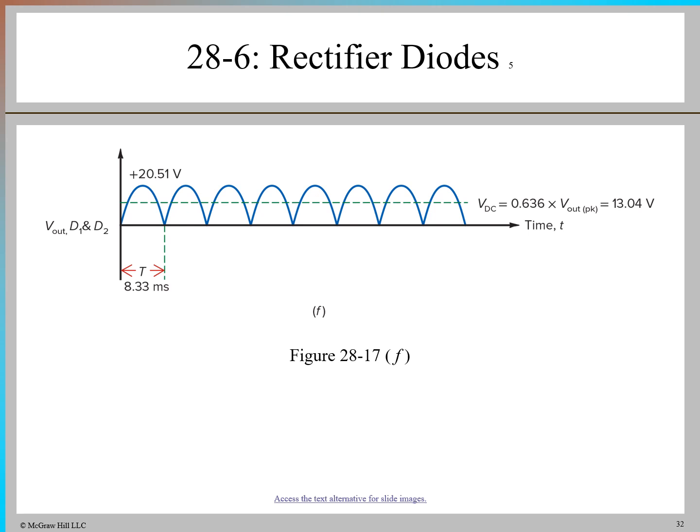The graph of a full-wave rectifier shows the transformation of an input AC sine wave into a pulsating DC output. Notice how both the positive and negative half cycles of the AC input are rectified, producing a continuous output above the zero line. The output frequency is doubled compared to the input, which results in a smoother current flow. The peak value of the output waveform is the same as that of the input, but the ripple or fluctuations are less pronounced compared to a half-wave rectifier.